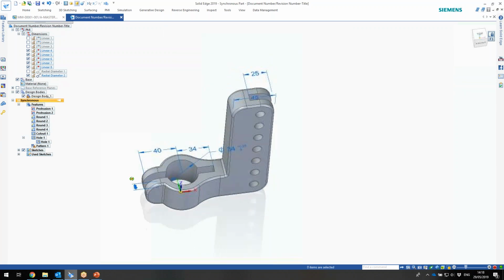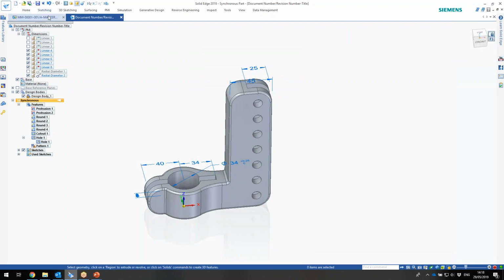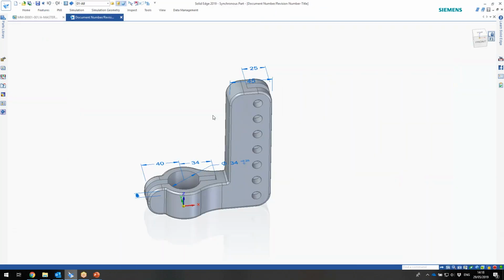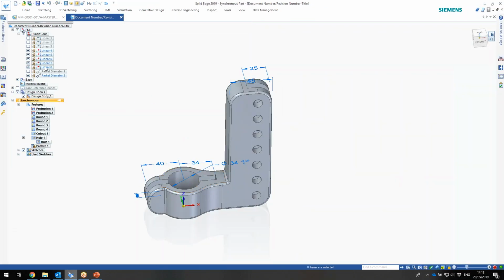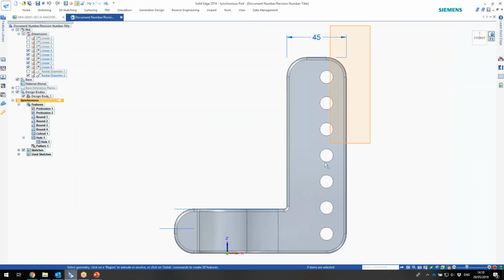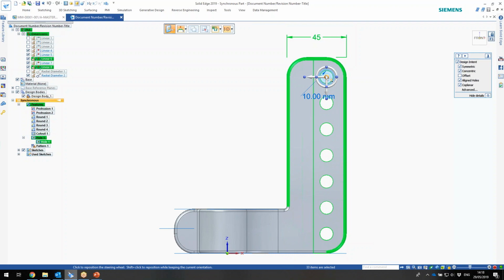Okay, brilliant. Now, one of the things I do know is that this pillar needs to be raked back towards this to create strength, because this is a cast aluminium part. So any fatigue points, we want to strengthen that as much as we can. So jump here. This edit here in a history-based system would be quite difficult to achieve.